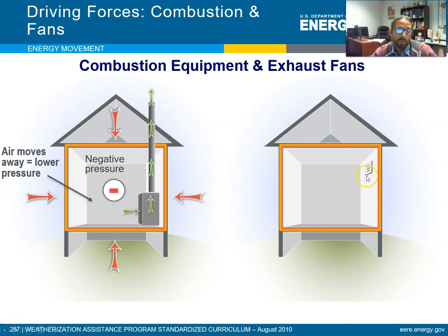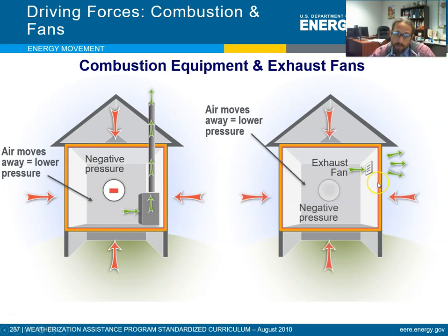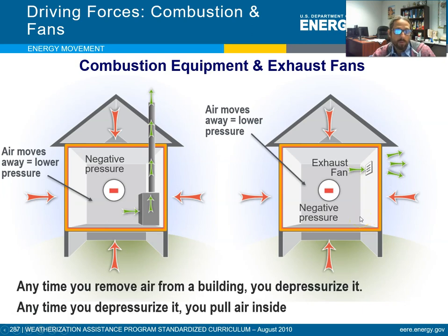Same thing if you have an exhaust fan. So if you have a bathroom exhaust, a kitchen exhaust, or a laundry machine that's exhausting air outside. When you pull that air outside, guess what? Same thing. You're going to depressurize the house, which depressurizes the whole building, and that's going to force air to come in from outside the building. So think about a real cold winter day and you're running the bathroom exhaust fan. Maybe you're also running the kitchen exhaust fan. Maybe you're also doing laundry, right? Now you're exhausting air here, exhausting air here, exhausting air here.